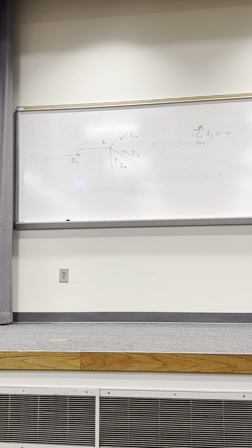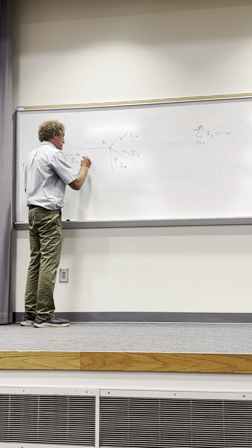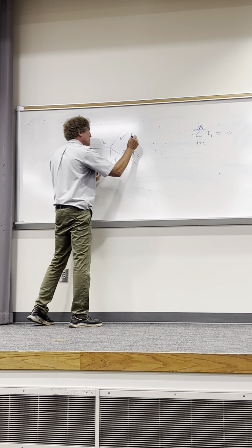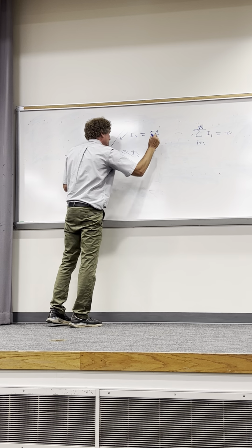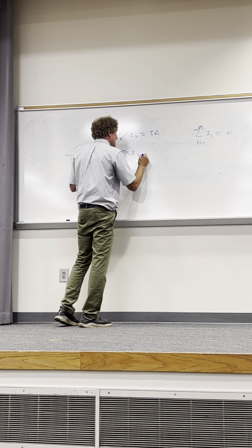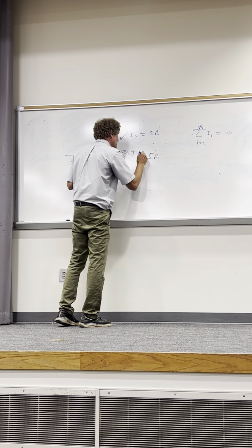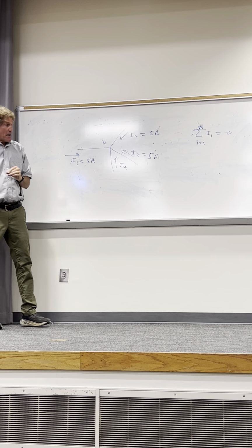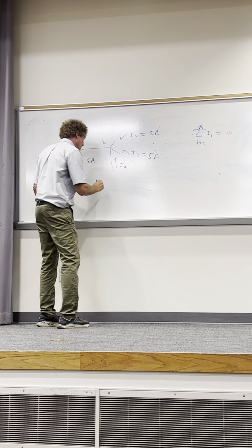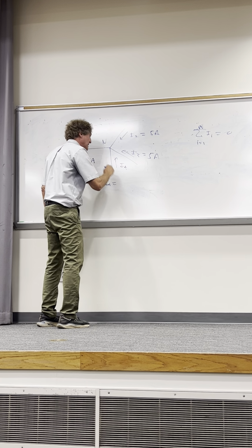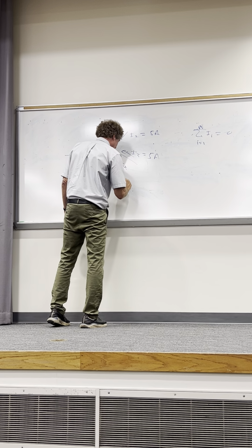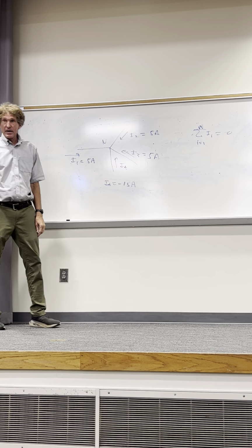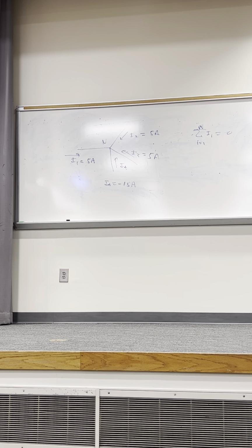Now here's the next step. If I1 was 5 amps, and I2 was 5 amps, and I3 was 5 amps. Remember, the direction of current is assumed positive. You all with me, class? That means that I4 has to be minus 15 amps. Whatever goes into it comes out of it. It doesn't accumulate. You all with me, class?